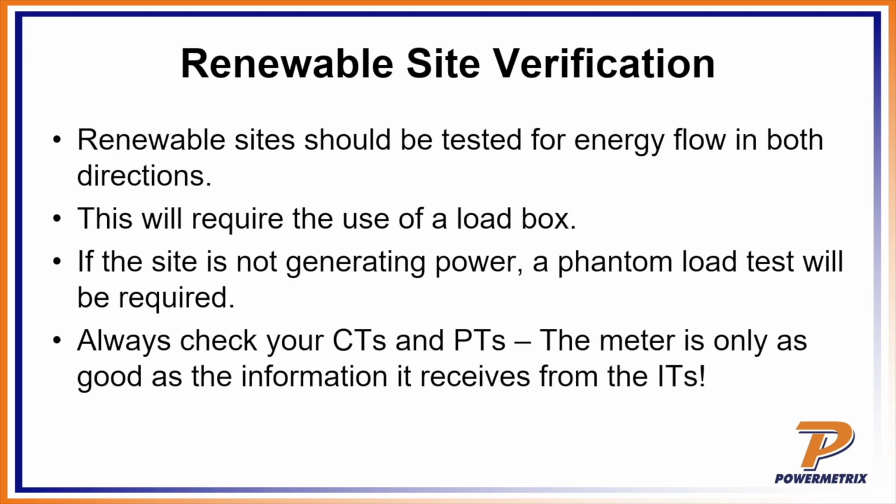And then finally, of course, for the renewable site, transformer rated site, be sure to check your CTs and your PTs. The meter is only as good as the information that comes to it. As we like to say in the electrical engineering world, garbage in, garbage out. So if your CTs are wired up improperly, even if the meter is registering 100%, if you've got a backwards CT, you're losing money. And so be sure and check that.